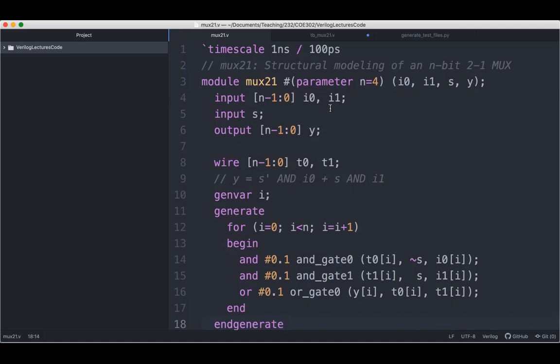I'm going to create an input file that contains the input patterns that test as much as possible from the input space, usually using random data, but a high enough number is sufficient. Usually random data with lots of patterns does a good job in testing the entire circuit.